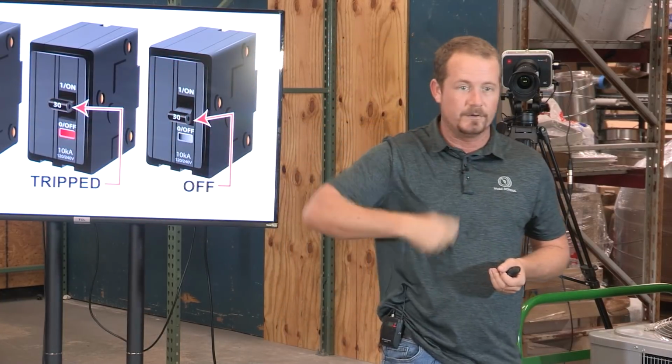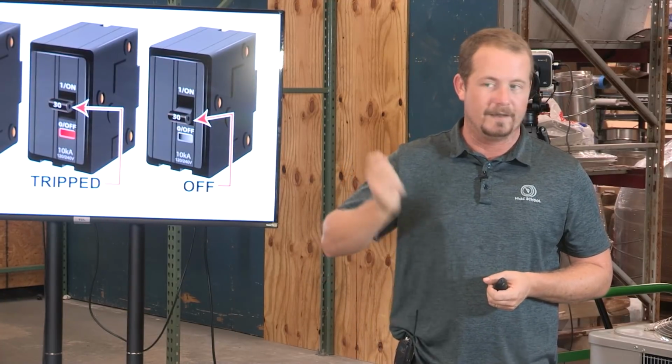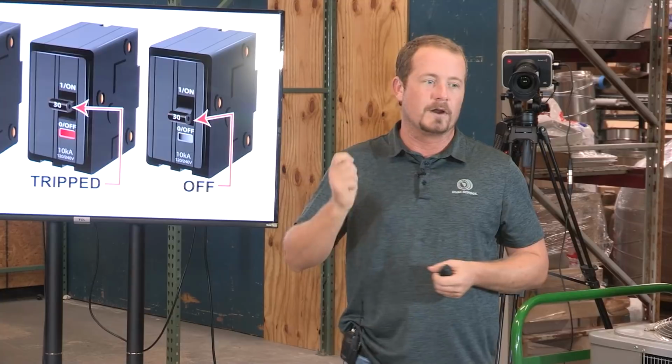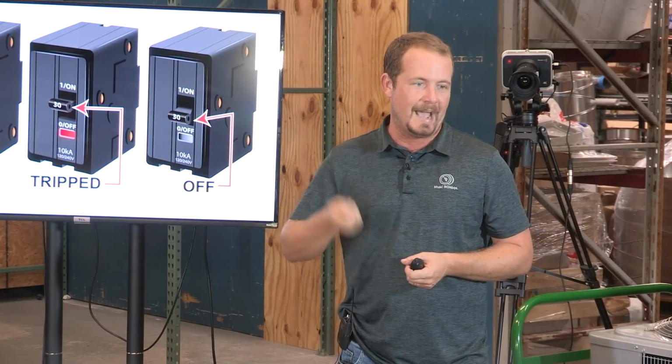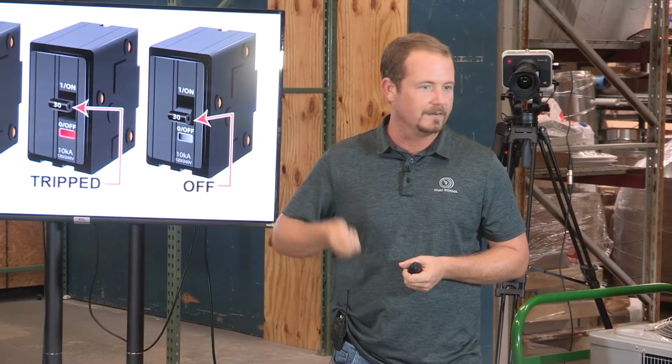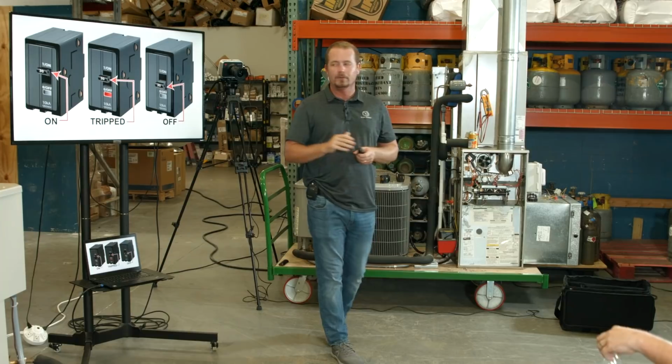You got a breaker that's tripping, you reset it, bam, it trips again, and then you just keep resetting it, right? Isn't that what you're supposed to do? Yeah, it's good, because if that compressor is shorted internally, now you're just creating more and more carbon and acid and sludge inside that compressor. It's great. That's what we want. Just keep resetting that bad boy, and just hold it in place. Try to hold it. No.